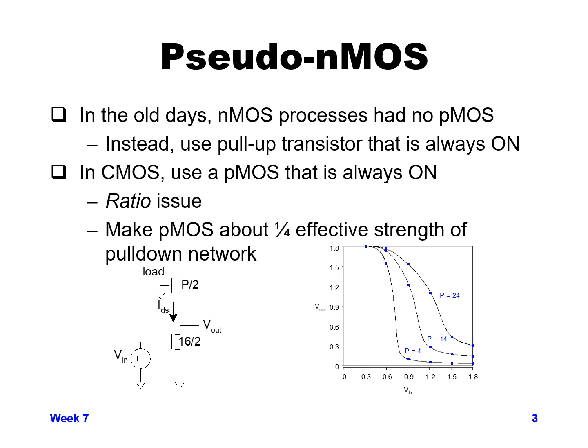And you can see that on the curve labeled P equals 4, the NMOS pulls pretty close down to ground. Now as P gets larger, so P gets to 14, it's not able to get nearly as close to ground. It still gets pretty low, but it's maybe getting to 0.2 volts instead of 0.05 volts.